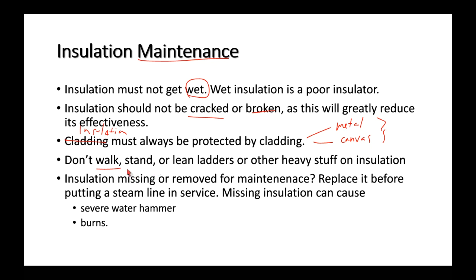We never walk on insulation or stand on it. We don't lean ladders against it. We don't put heavy stuff on insulation because it's going to compress it. It's going to damage it. It's going to reduce its insulating value. If insulation is missing or hasn't been replaced, replace it. And if it's not replaced immediately, people might get burned or water hammer. So let your maintenance people know.